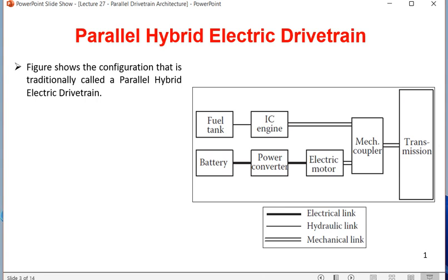A normal battery is generally a high specific energy source, but the battery connected here in case of HEV is designed in such a way that in a very small time it should be able to give very high power. So it will function mainly for 10-15 minutes and will get discharged. So this battery is designed specifically as a high specific power source.